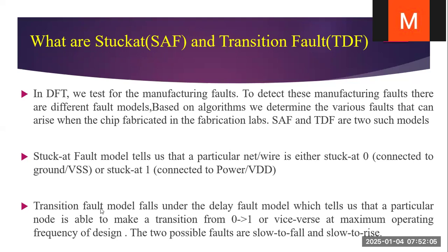The transition fault model falls under the delay fault model, which tells us whether a particular node is able to make a transition from 0 to 1 or 1 to 0 at the maximum operating frequency of the design. The two possible faults are slow to rise and slow to fall.